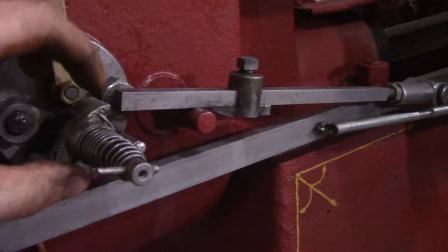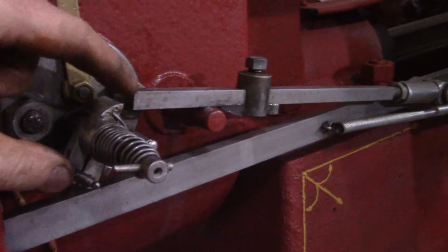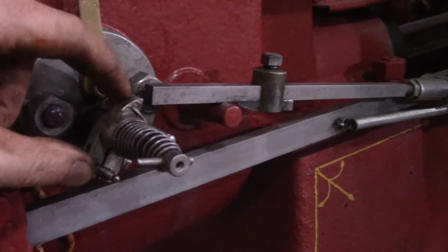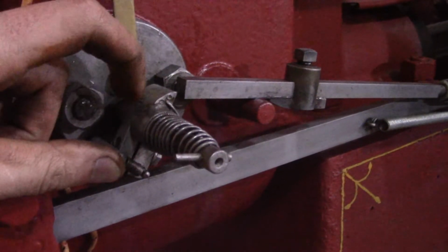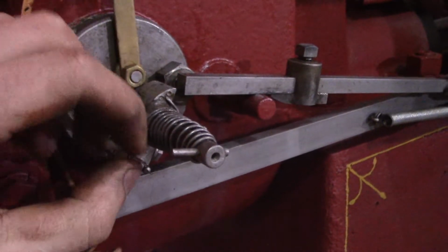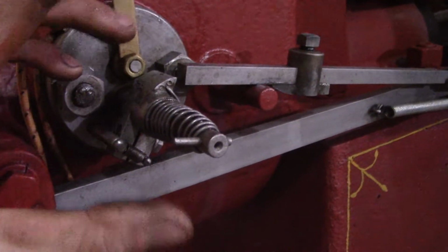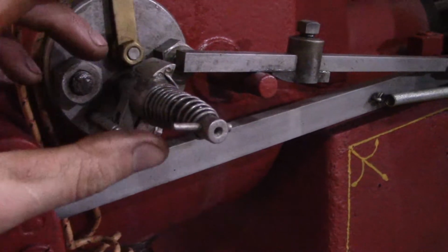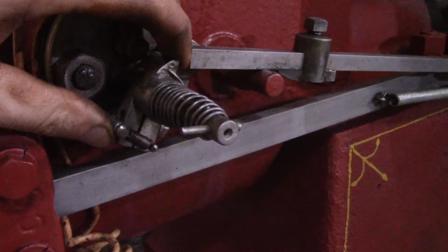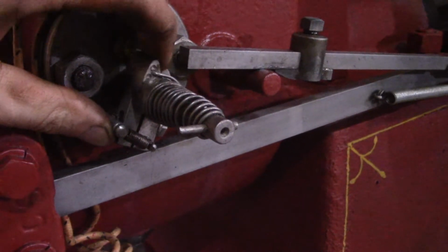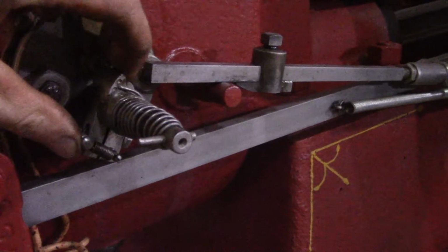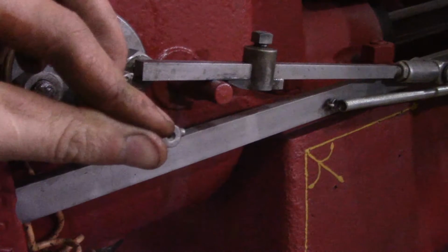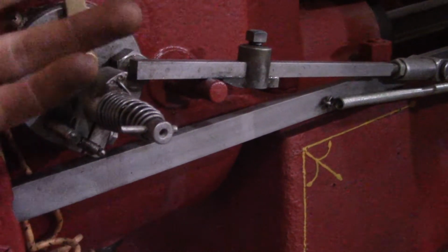When it raises it up, it'll delatch the trip rod from the trip here, and then it'll snap open, and when it opens, that'll make a spark and make it fire. But the reason there's this extra springy thing here is so the push rod can continue to push this, and it's not just forcing the points together harder and harder and making it break something.